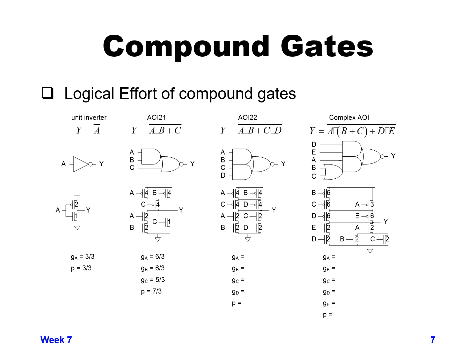is the logical effort. And for the C input, we have a size 4 PMOS device and a size 1 NMOS device, so we have 5/3. And then for the propagation delay, we have to sum up the total capacitance on the output Y. So we have 1 PMOS device of size 4, and then 2 NMOS devices, one of size 2 and the other of size 1. So we add that all up and we have 7. Normalized against the inverter is 7/3.